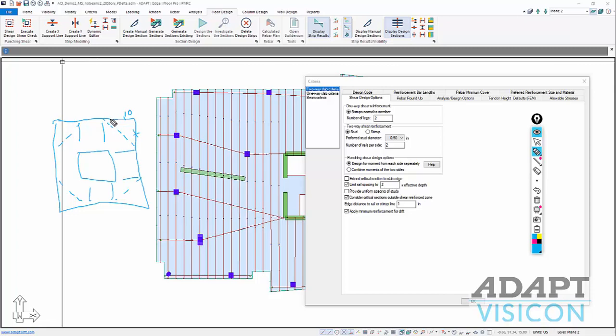When there's no reinforcement required, this is at a distance d/2 from the previous section, which would be layer 9, which required reinforcement. So this is the first critical section not requiring reinforcement. We come back and we check it with this reduced critical area. And if we need reinforcement, we continue to check this. If that stress is greater than the allowable 2 square root of f'c, then we come back and we recheck another octagonally shaped section.